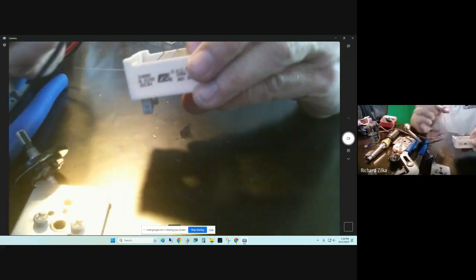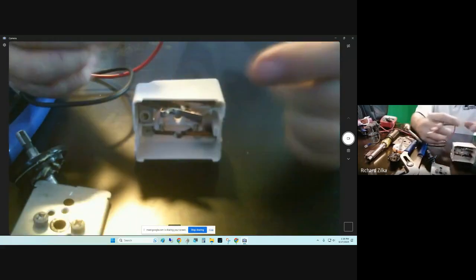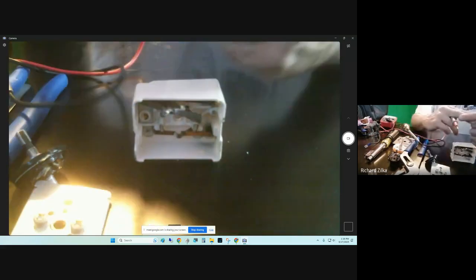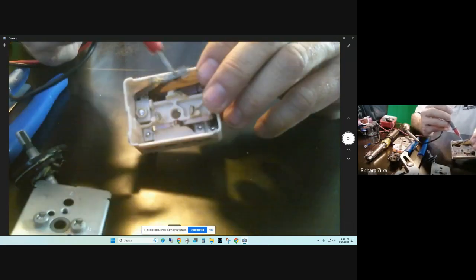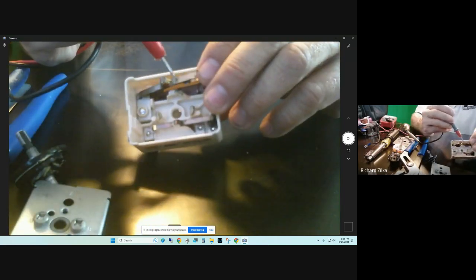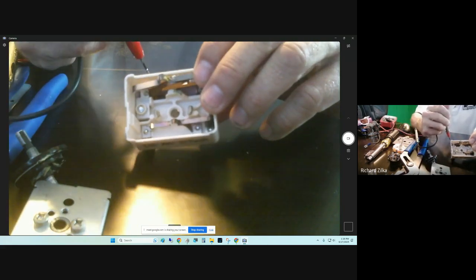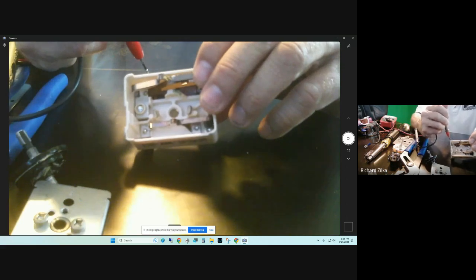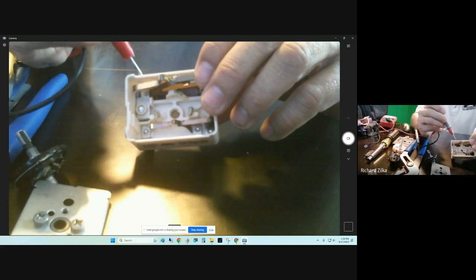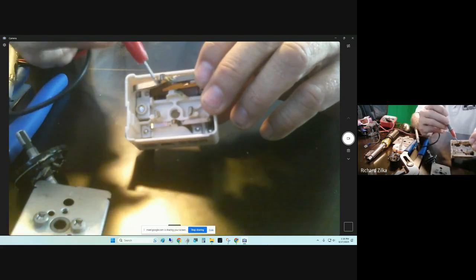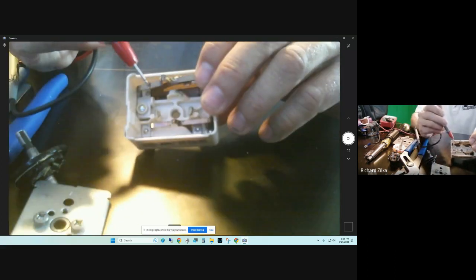Now, on the old coil type burners, not the glass top stoves, I don't know if any of you guys changed those little terminal blocks that the burner plugs into because they burn out. Well, sometimes those wires touch ground and they short this and they damage a switch. So if you got a customer with the old style burners, those round coil burners, and they tell you, yeah, the burner works, but it only works on high. I can't turn it down. It's just on or off. Well, okay. Before you change this switch, lift up the top and make sure that there's nothing there that shorted and damaged this switch in the first place, or otherwise you're going to change the switch and blow it out again. So this was L2 to H2.